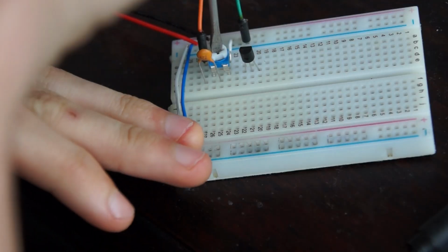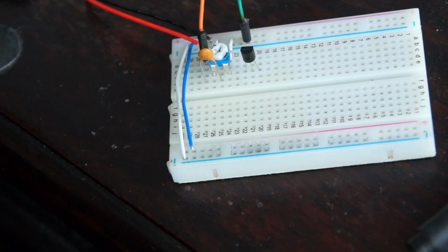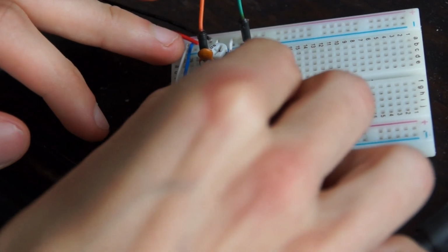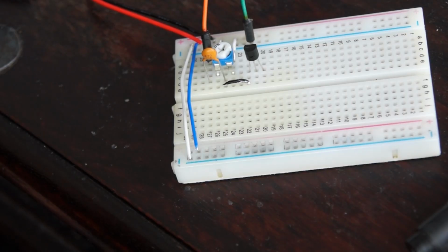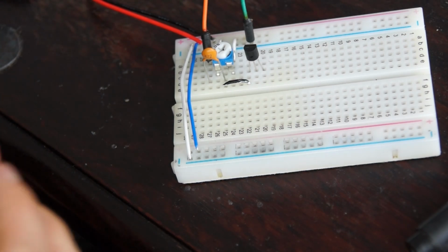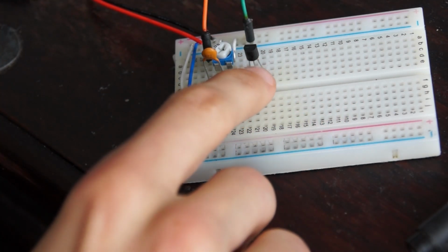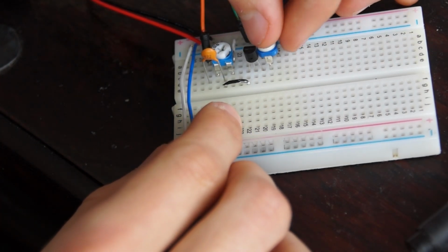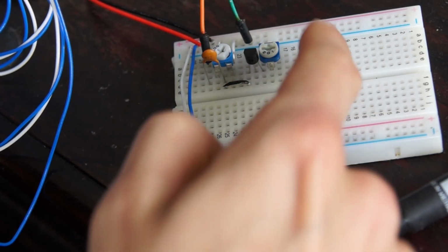I'm going to put it on about 10% to just raise the voltage a tiny bit, or lower in this case. And of course the output of our voltage divider has to be connected to the base of the transistor. The next thing I'm going to set up is our gain resistor, and for that I'm going to use a 1K trim pot, and our emitter is the rightmost pin on the transistor, so I'm just going to connect this gain directly to the emitter. Now I need a little cable that goes from the trim pot to ground.